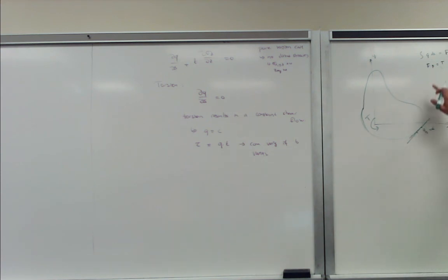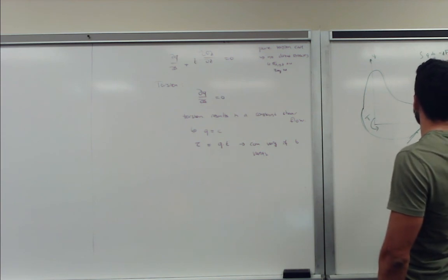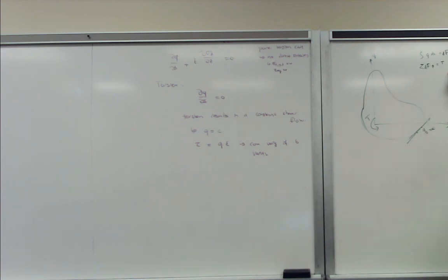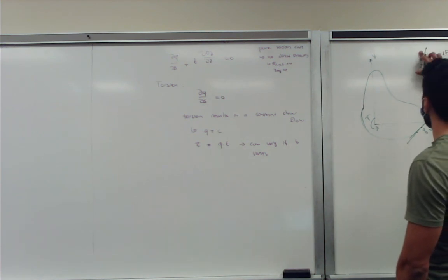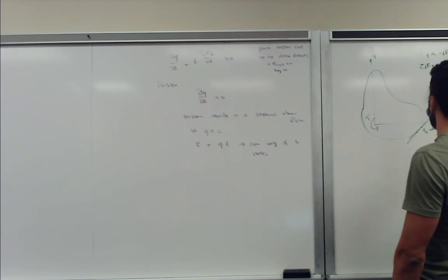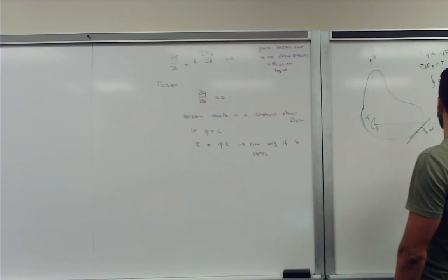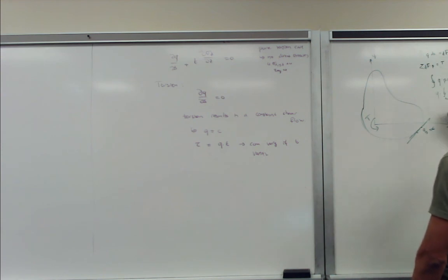So of course, we take a segment ds, we know we get a segment dF, and if we want to compute the whole torsion, we basically compute the summation of all those small segments. So if we do this, we should take the integral of q ds. If we want to do the summation of all the moments, that's basically equal to the integral of q times p ds. q in this case was a constant, so we get the integral of p ds multiplied by q.